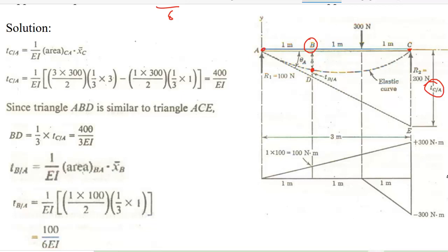In this technique, there is a way that you cannot combine several loadings to draw the moment diagram. Suppose in a beam you might have different kinds of loading, maybe UDL and point load. While we draw the moment diagram, that moment diagram is combined. We don't know what the degree of action will be, and we don't want this kind of complex situation. So what we will do is draw the moment diagram separately for each individual force.